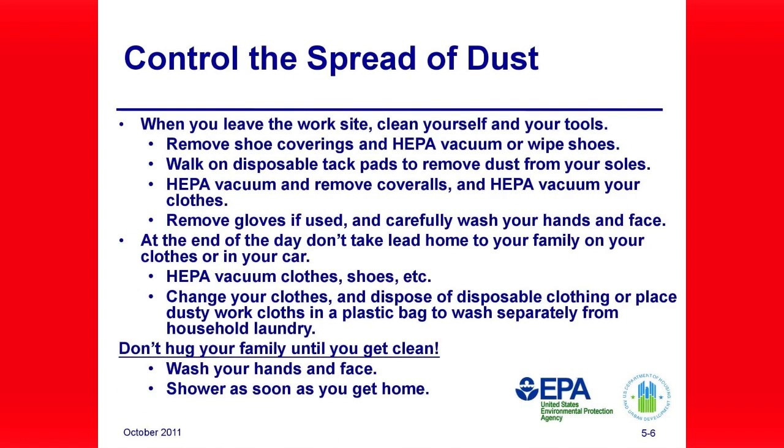Control the spread of dust. Precautions to take when leaving the work site. When you leave the work site, the area covered by protective sheathing or the workroom, take precautions to prevent spreading dust and paint chips on your clothes or shoes to other parts of the residence. Every time you leave the plastic sheathing around the surfaces being renovated, remove the disposable shoe covers and wipe or vacuum your shoes before you step off the plastic sheathing. A large disposable tack pad on the floor can help to clean the soles of your shoes.